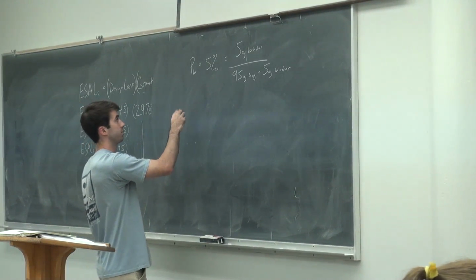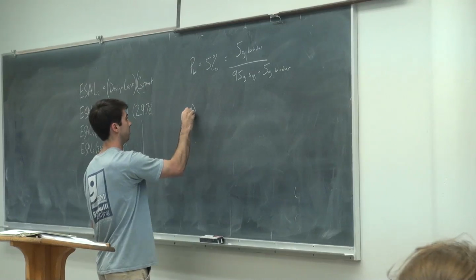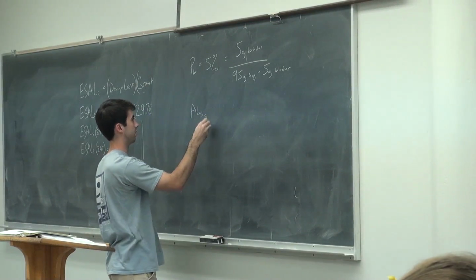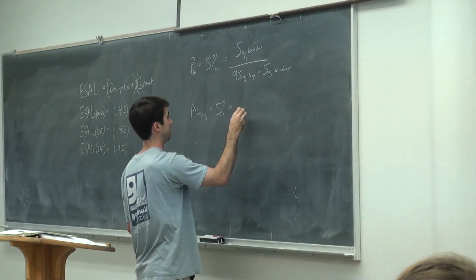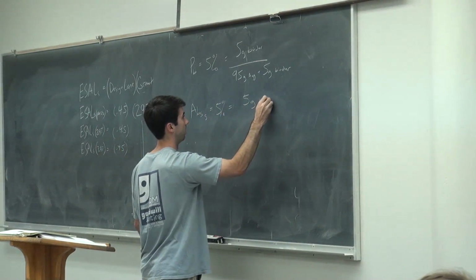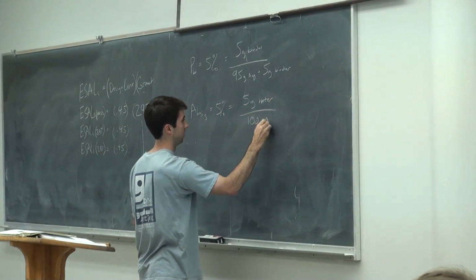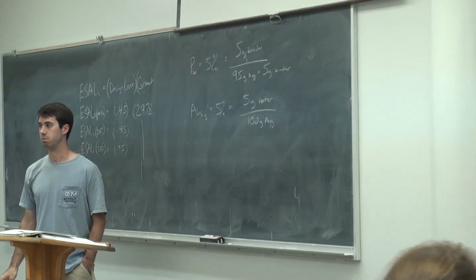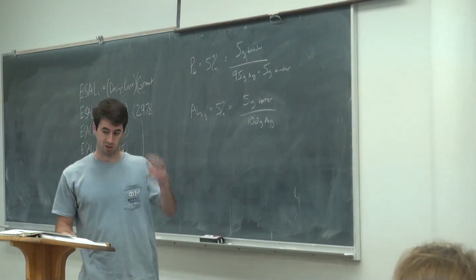So if you, does that make sense? Like if you had an absorption for some, we'll just put S there, in stone, and it's 5%, that means it's 5 grams water out of 100 grams aggregate. See the difference? So there's little differences in the terminology. Make sure you keep those separate.